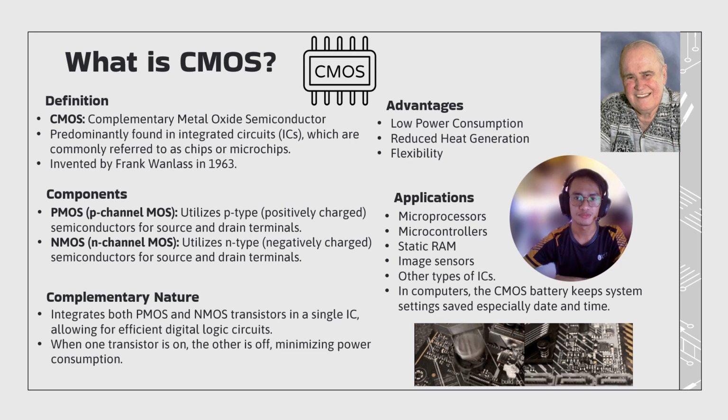Before CMOS, both PMOS and NMOS were standard. NMOS was preferred for being faster and cheaper but had drawbacks like static power consumption. So the advantage is that CMOS combines PMOS and NMOS in one IC. It offers symmetrical PMOS and NMOS pairs. This combination improves the design flexibility, reduces complexity, and minimizes electronic noise.